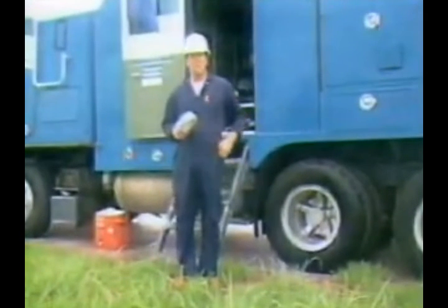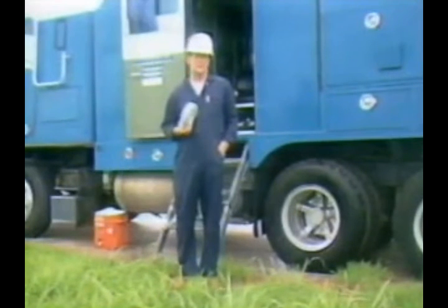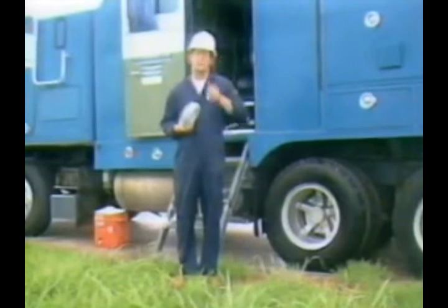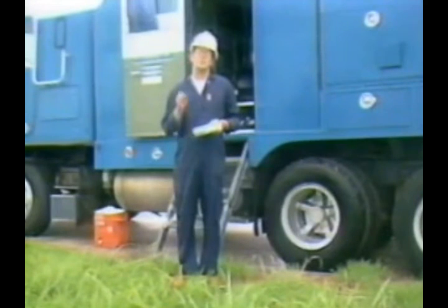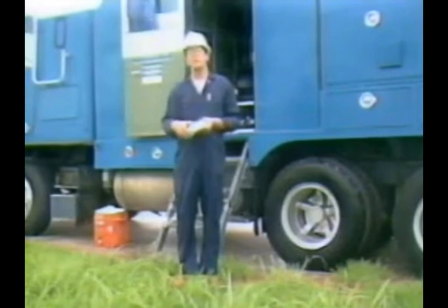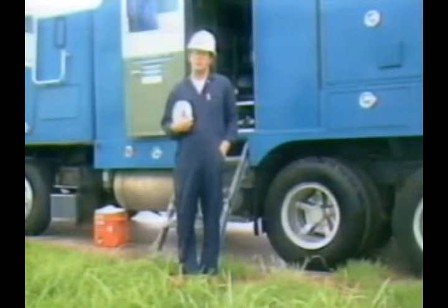But determining if the newly perforated well is performing up to expectations requires some test data to assess the efficiency of the completion. Tools are now becoming available that will allow the engineer to immediately measure downhole pressure, rate, and temperature, even before the guns are retrieved, allowing for the selective reperforation of any poorly performing intervals.